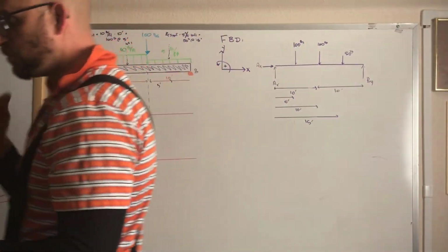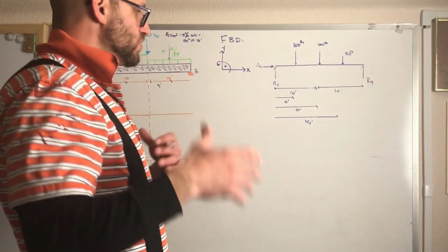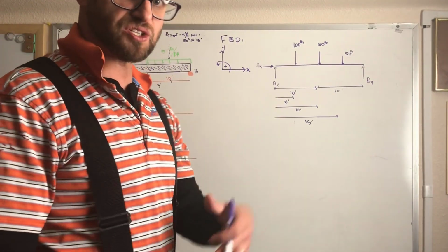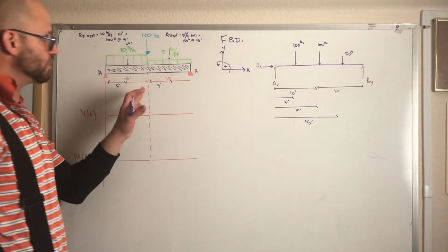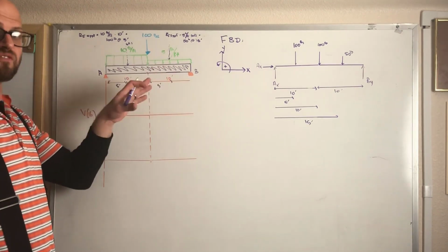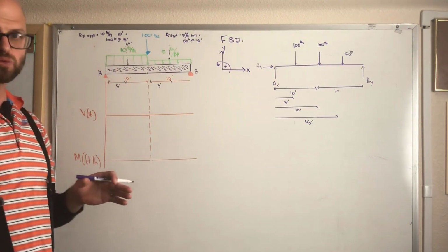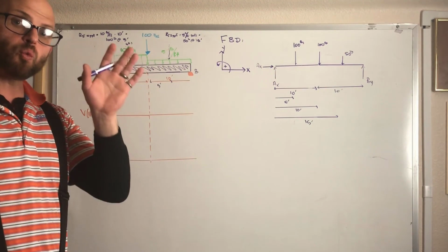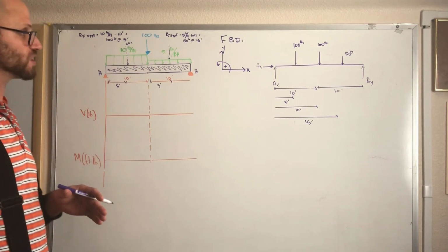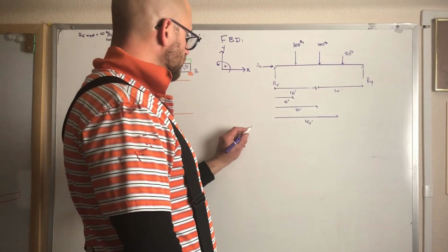Now please bear in mind, we're still going to take into account that these are distributed loads, but when we're trying to figure out the moments and what have you, we have to write that representation of what that reactionary load is and where it's going to happen. When it comes to a rectangular distributed load, we go with the center of that rectangle. If it's a triangular load, we're going to go 1/3 from the peak, the tallest peak of that distributed load, for where that reaction is going to be. Okay, so we got everything written in. Let's go ahead and start doing some math here.